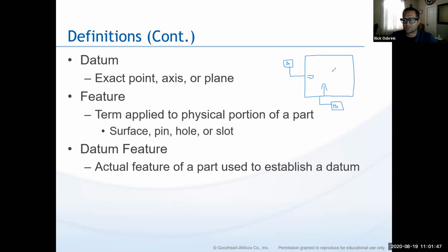So if I have a true position, let's say I have a hole right here and I need to position that hole, I'm going to have a measurement from here to center line, and I'm going to measure from here to center line, okay? Now this is really important to maintain these datums, because if we're trying to make components that fit together, I don't want to just start using edges at random because there's free space. So if I have a hole over here, I don't want to say, oh, it's closer to this edge, so I'm just going to give a measurement from here and from here, okay? That's not using our datum points, and then we can have those tolerances stacking up. So in this instance, I would give a measurement from here and a measurement from here in order to give a correct true position.